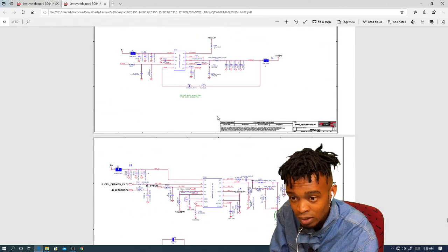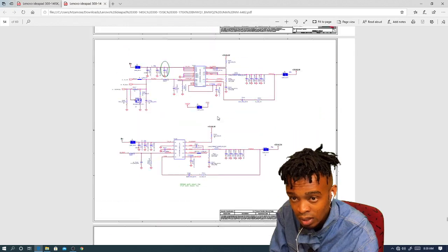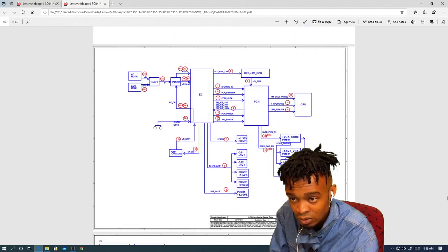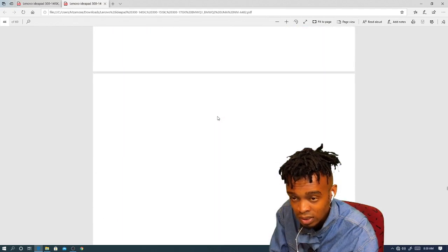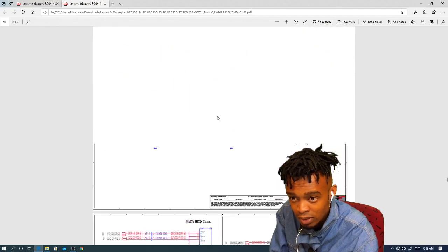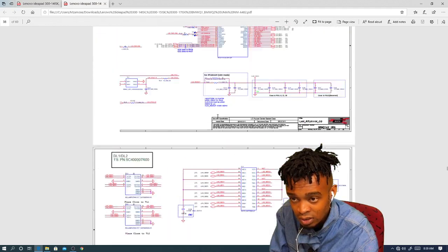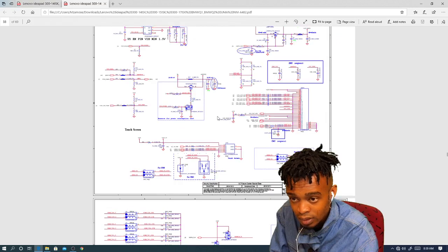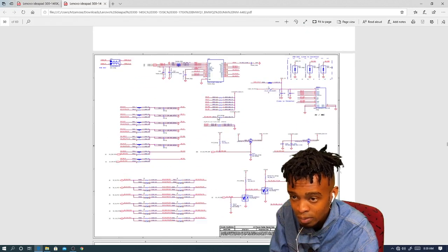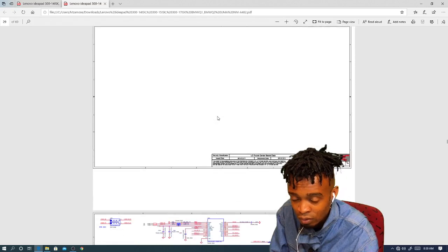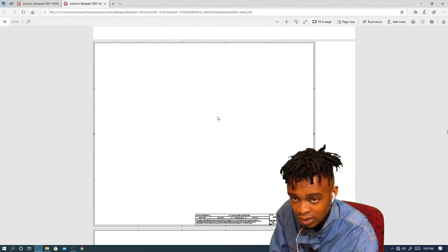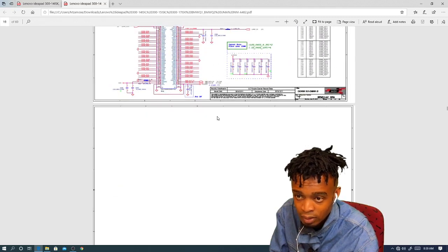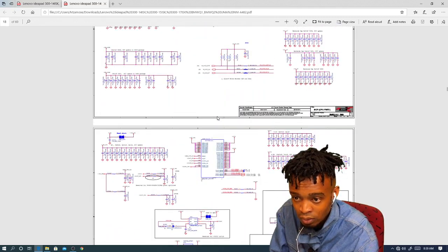You all know that the 3.3 and the 5 volts are important. Before anything else, you need the 3.3 volts and you need the 5 volts. Let me show you how they are generated on the latest motherboard. Even if you are missing the 3.3 or the 5 volts on the latest motherboard, this is where you should check first.